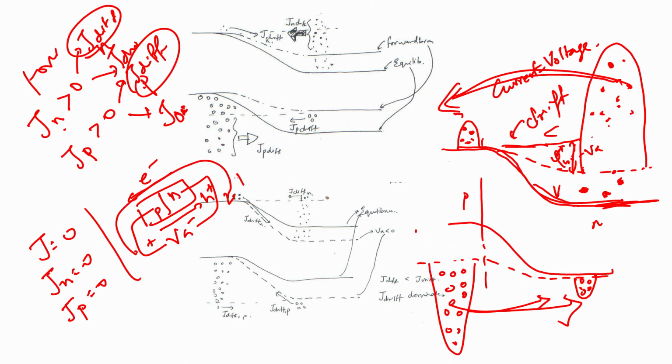So it is a very large current that goes through, and a small increase in VA reduces the barrier height a little, but since the diffusion component, or the electron population, is exponentially dependent on the voltage, you find that the electron population scales up very rapidly as you change the value of VA. Therefore, the diffusion is quite a powerful component in the current.